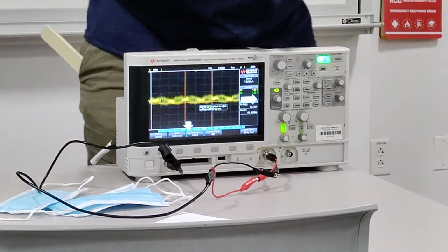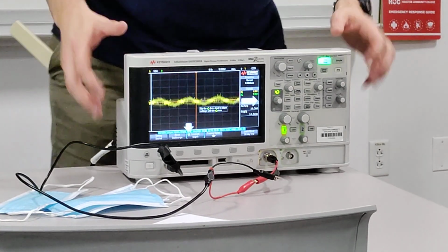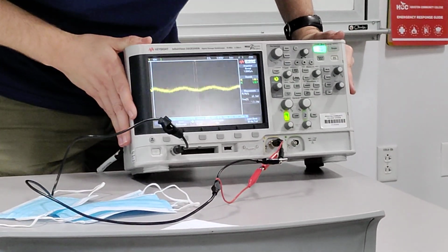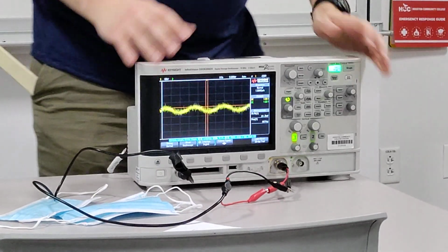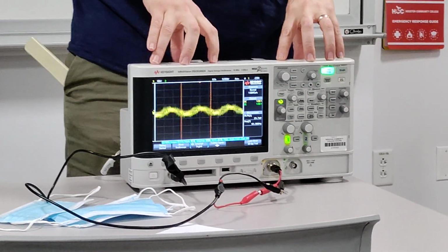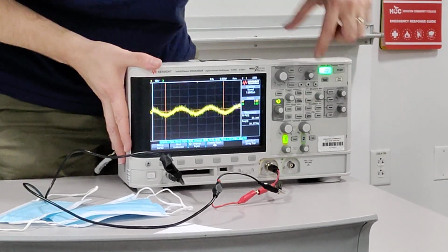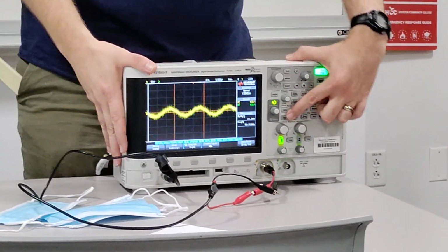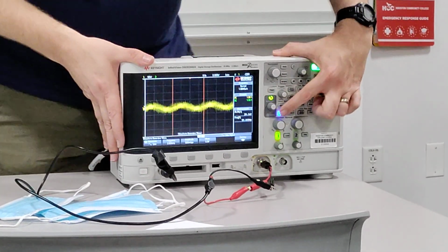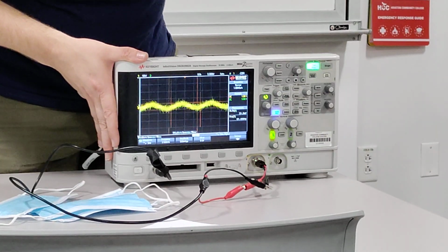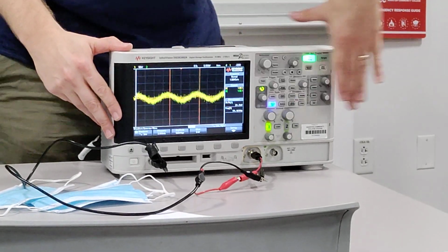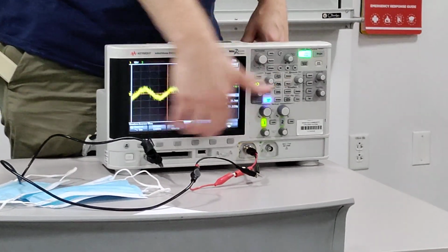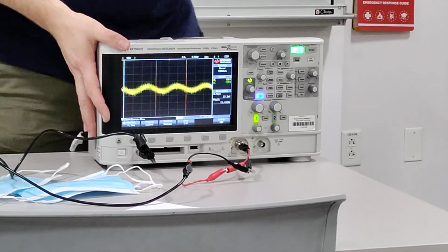Okay, so we are on. This is sort of a normal initial screen. So what we're going to do first is set up the function generator to be outputting anything at all. That is this button that says wave gen, so that's wave generator. If I hit that button, then all the buttons on the bottom of the screen are going to change. This is true of pretty much all of these buttons. You hit that and then the bottom of the screen gives you options that you can adjust.